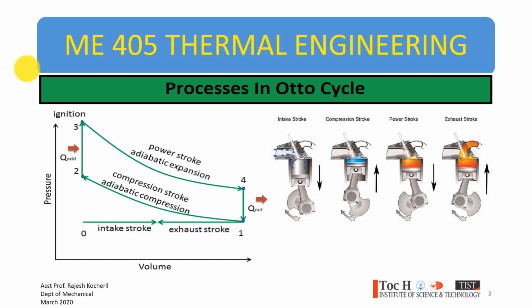When the piston moves down, the volume is increased, and subsequently the temperature and pressure inside the cylinder also reduce. And when the piston reaches bottom dead center, at that time the exhaust valve is opened and the flue gases which are remaining inside the cylinder will start moving out. In actual cycles, this valve opens some degrees before BDC, and at this time the inlet valve is opened because after the exhaust stroke, the next process is the inlet stroke.